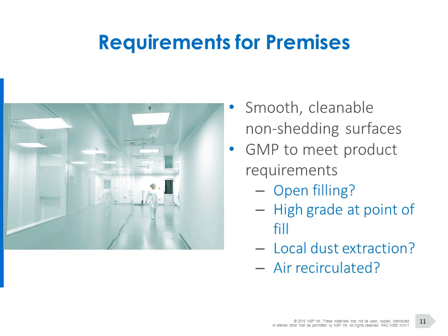Then looking at the actual facility, the premises, it's important to have smooth, cleanable and non-shedding surfaces, particularly if you have open product, and to also have a higher grade of air at point of fill, as I've already said. But don't forget the local dust extraction that may be required and air recirculation.